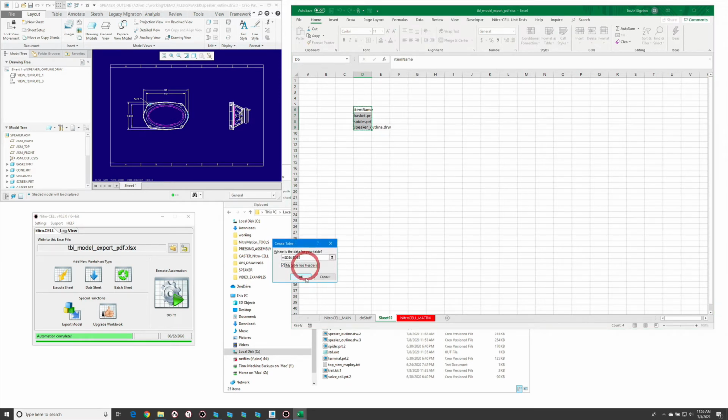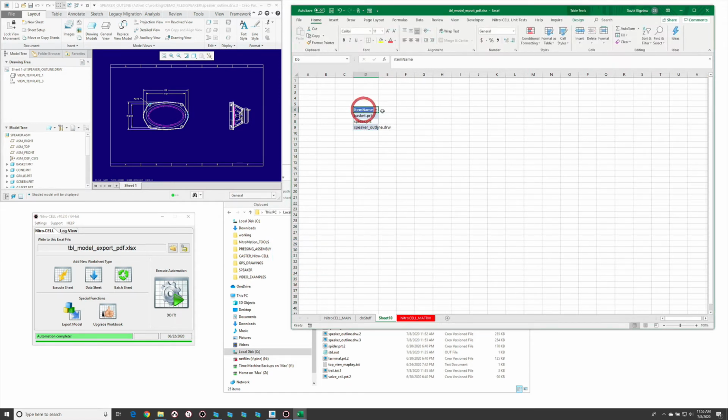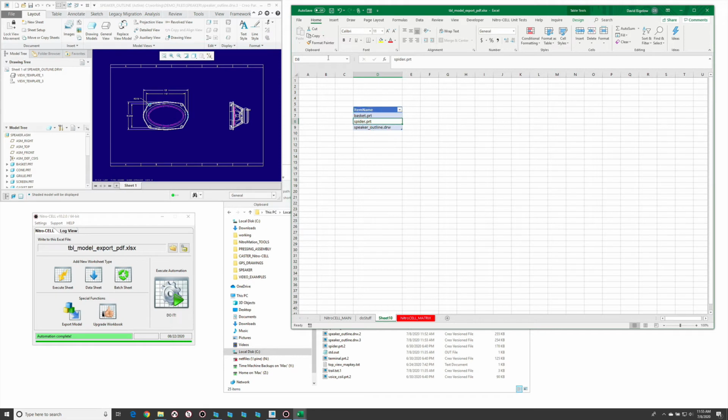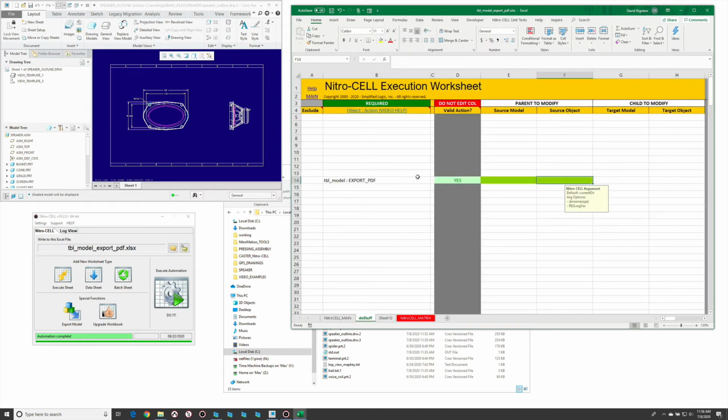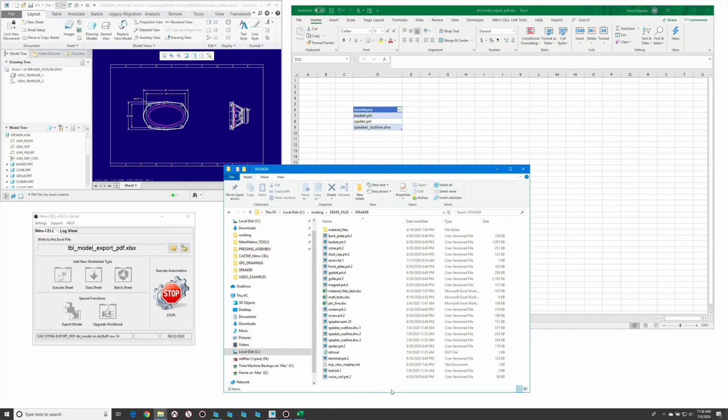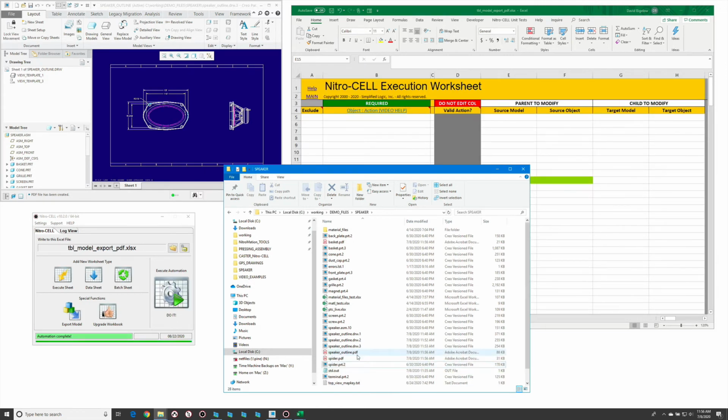out of this in Excel. And I'm going to say the first record there is going to be my header. And then we're going to give that table a name of my table. Okay, so that's the reference we're going to use. So I'm going to use TBL colon my table, and we'll just press the do it button, and we should see as it iterates through each of those items here, we get our various PDF files generated.